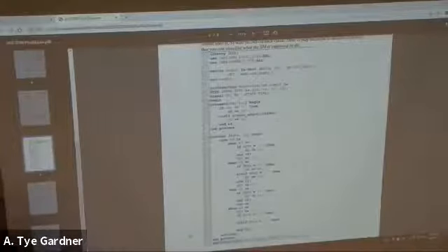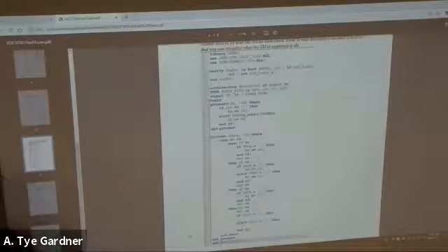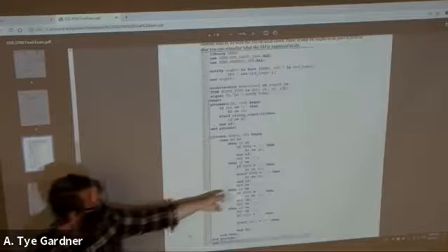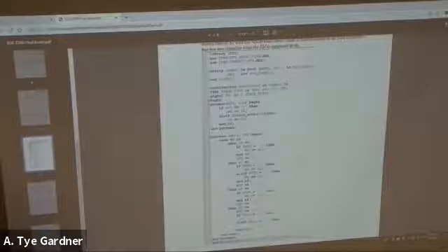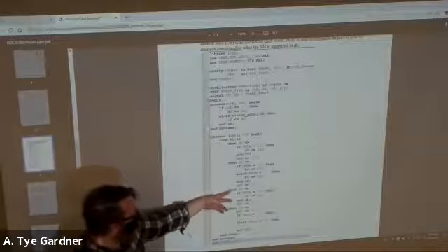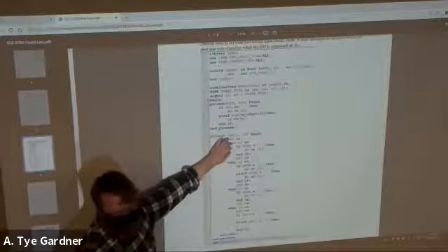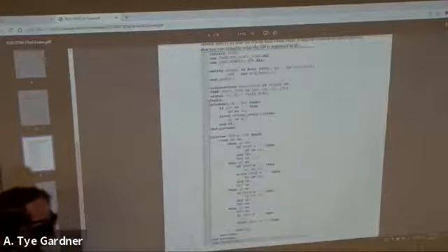They will both work. Because else if will work, you'll never see the don't care as long as I've covered all possible results. Now, you're kind of correct, right? Because if I get like an X or a Z, well, I don't know. Because that data type is standard logic, so it could be other things. But for 1 or 0, I'm complete. Okay. But yeah, if you wrote else, you'd be fine as well. And we have the same kind of issue in S2. The reason is last semester I didn't make as big of a deal about doing the elses as I did this semester, so I didn't worry about that in the code.